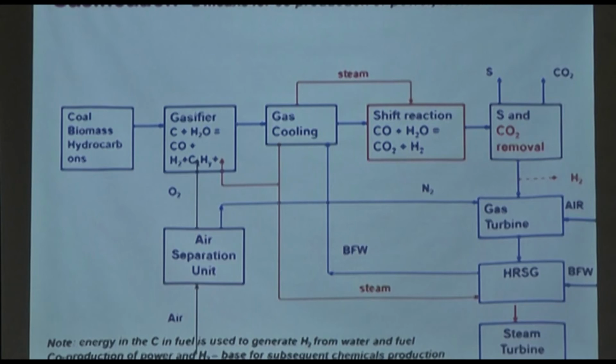The important thing in here is that we are providing a lot less oxygen compared to a combustor. And you can actually literally get any gas that you want in any proportion, carbon monoxide and hydrogen, in any proportion you want. And that has a distinct advantage, because if chemicals production is a focus, and it is becoming more and more of a focus rather than power, then for coal gasification there is no substitute at all.